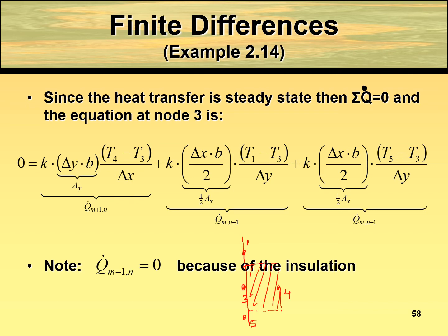So what you need to do is calculate the heat transfer coming in here, here, and here. So perhaps I'll draw it here again. This is the half node that you have, right? These are node 4, node 3, node 1, and node 5. We need to calculate the heat transfer from here, here, and here.